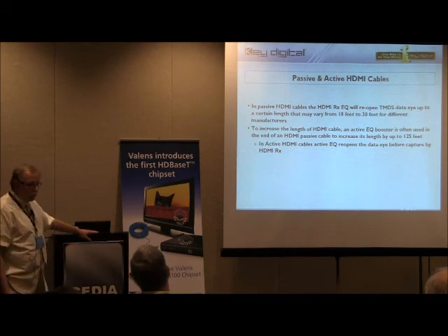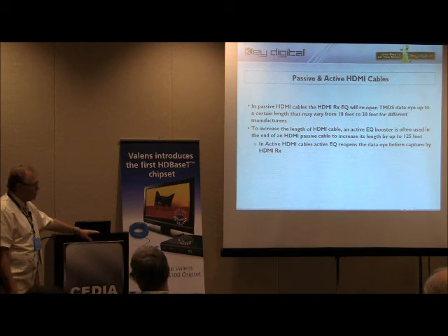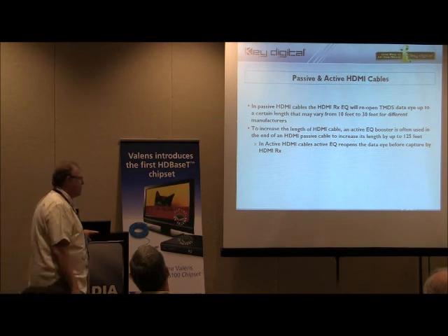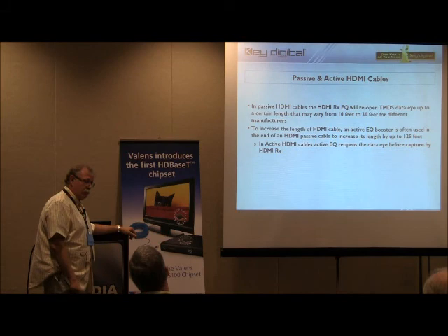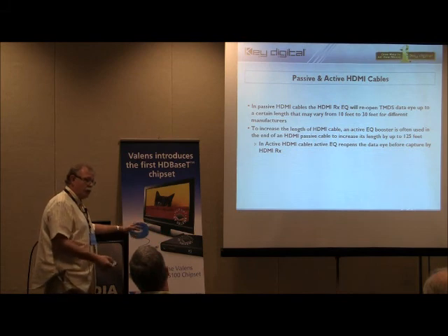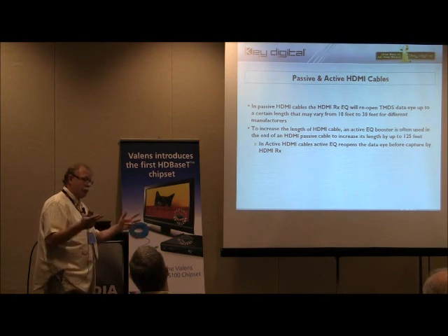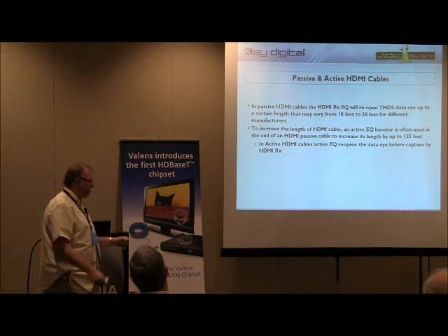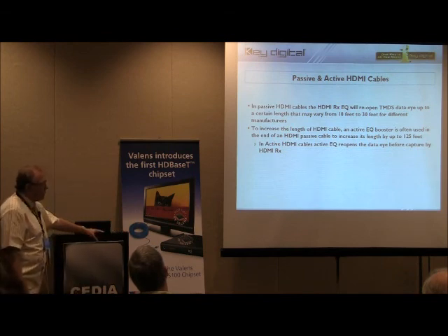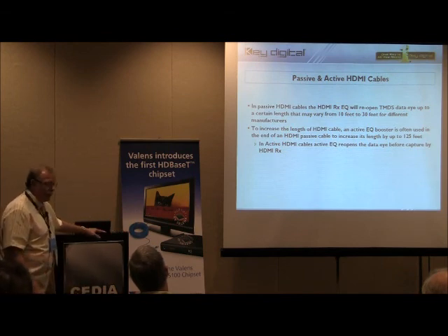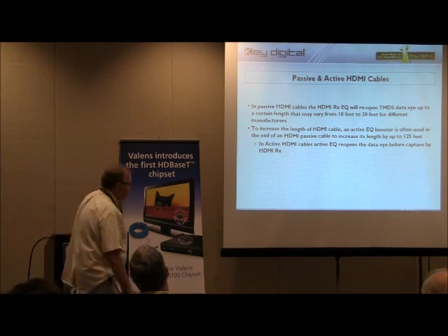Why is that? Cost. The cables that are 125 feet are very expensive to make, and an additional thing is ease of installation. It's much more difficult to pull a 125-foot HDMI cable than Cat5 or Cat6 cable that you can terminate yourself to the length that you need. So the balanced extenders, using Cat5 and Cat6 wiring, completely cut this product out of the market.